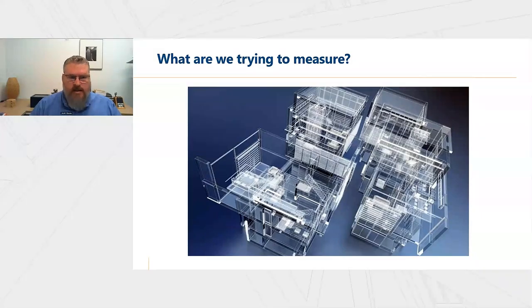But you've got things like stairwells that open to the exterior, you've got mechanical rooms, you've got loading docks, sometimes equipment rooms and other things that also open to the exterior that often aren't fully conditioned. So what's included there? Where is your air barrier? Is it at the loading dock door, or is it actually at the back wall of the loading dock, because those doors can be open all of the time?